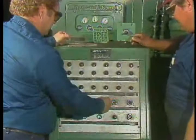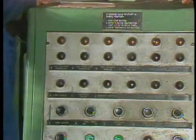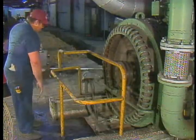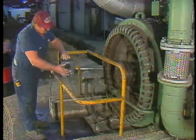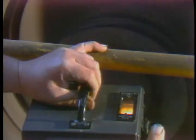The motor will draw high current and overheat if it does not pull into synchronous speed fairly quickly. If you find a synchronous motor running below synchronous speed, the motor may be overloaded. The stator windings, rotor windings, brushes, or rotor supply may be bad. If the problem continues, the motor will burn out.